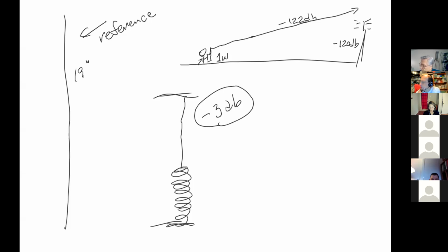So I start with 0 dB, and then I have a minus 122, which is lower than that minus 120 threshold. Will I be heard? Yes or no? I will not. But how about if I came over here and I used the same radio, and my path loss, because I was a lot closer, is minus 114? Will I be heard? Yes or no? Yes, I will. So even with that crappy antenna, because I'm at a better spot, literally at a better place, this person gets heard and the one further away doesn't.